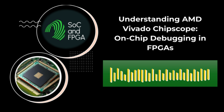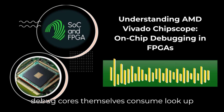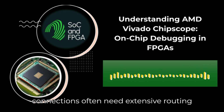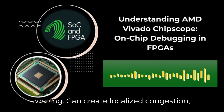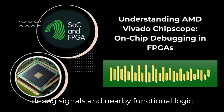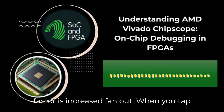Several root causes. One is simple resource congestion. The debug cores themselves consume lookup tables, LUTs, and flip-flops, FFs. But more significantly, their probe connections often need extensive routing across the chip fabric. This extra routing can create localized congestion, forcing the place and route tools to use longer, less optimal paths for both the debug signals and nearby functional logic. Crowding things out.